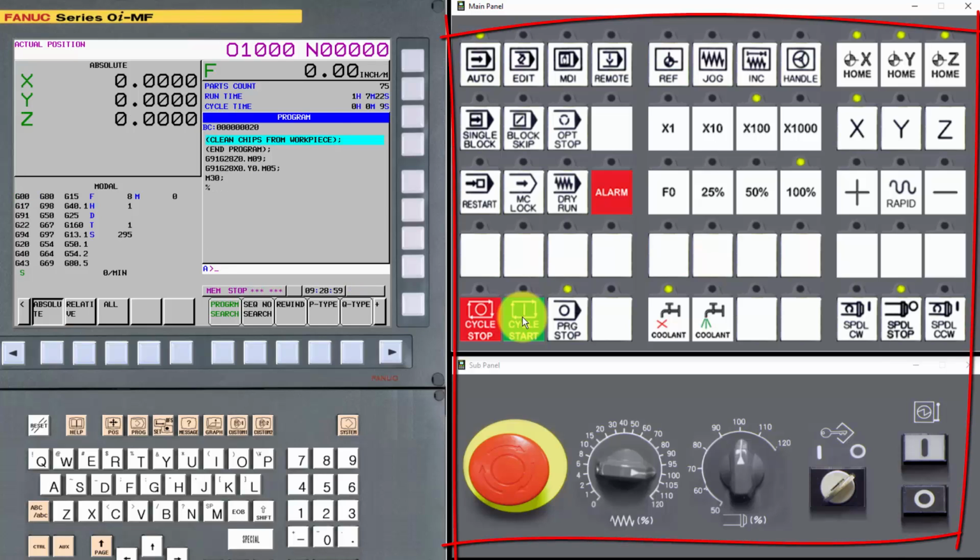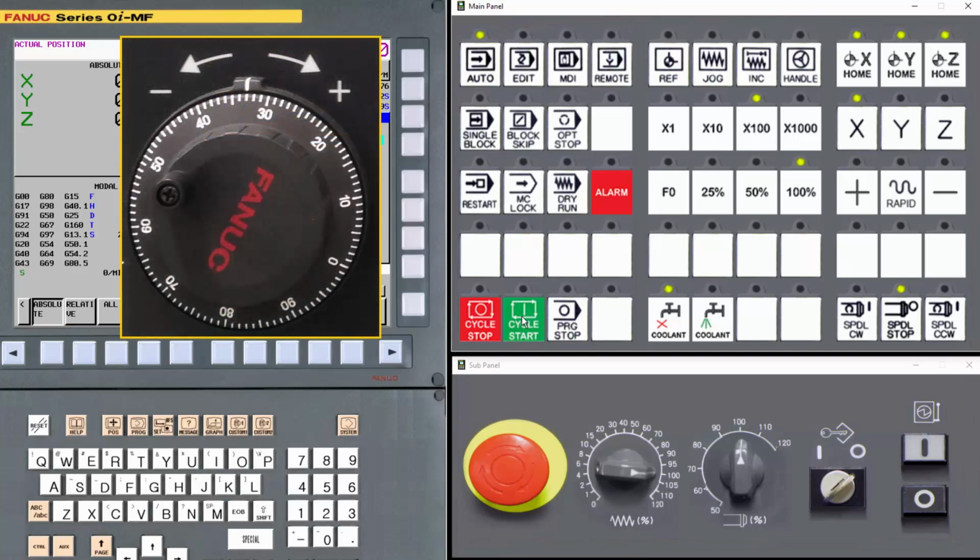For this tutorial, we will use this generic machine operators panel, an implementation of one of the generic machine operator panels available from FANUC, and it also includes most of the basic functions to run a program. One item it does not include is a hand wheel or MPG, which is an abbreviation for manual pulse generator. The hand wheel is an ideal way to manually move the axis, and it works pretty much like a hand wheel on a traditional machine tool, except the connection to the axis is electronic fly-by-wire rather than mechanical. They are particularly useful for setup, allowing rapid, slow, and precise movement as required.